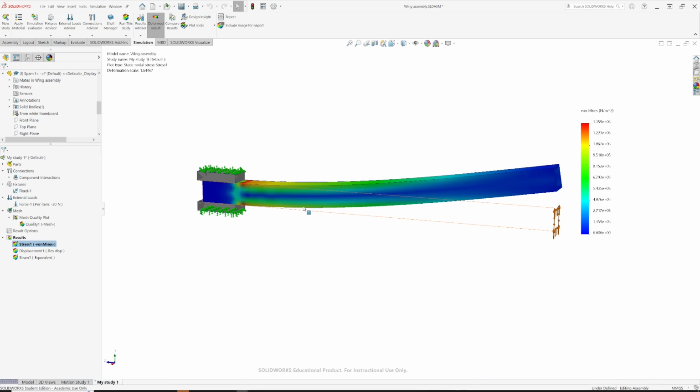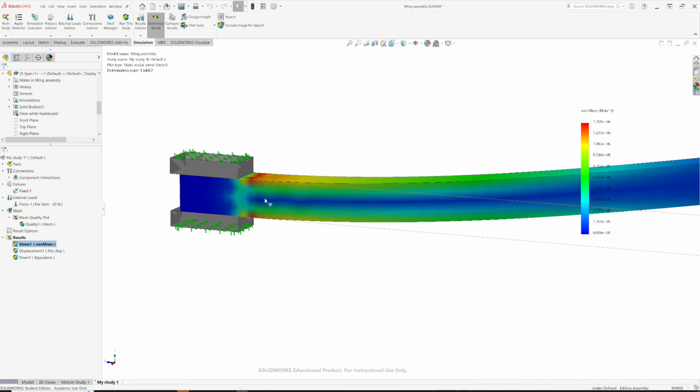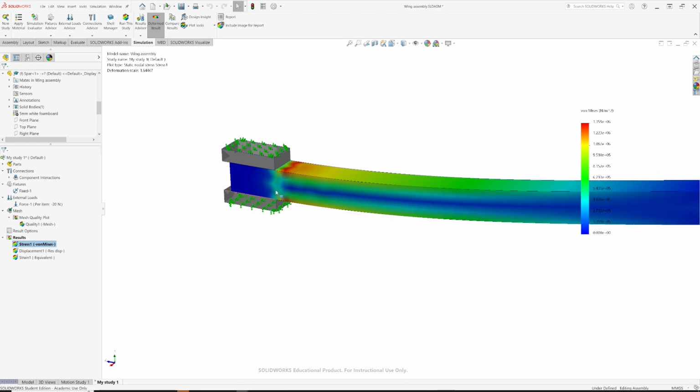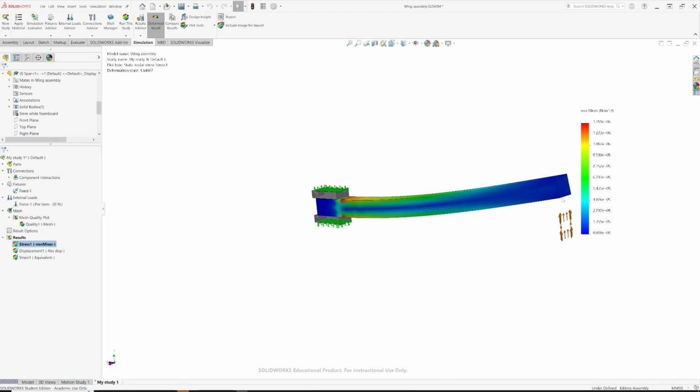The beam's obviously gone up at that end, and this plot here is von Mises stress. It doesn't have a direction, but it's the kind of average stress in the material. You can look up what the definition of it is, but in terms of tension and compression, it's this kind of magnitude of stress. What this is saying is our peak magnitude of stress is at the top and the bottom at the root. And if you know anything about structures, that's exactly what you'd expect. We applied a load at this end, and the stress at this end is almost nothing. All the stress is at the end where you've clamped it,